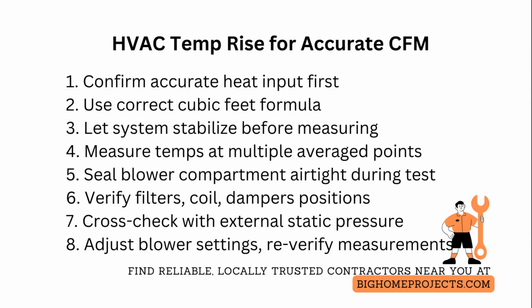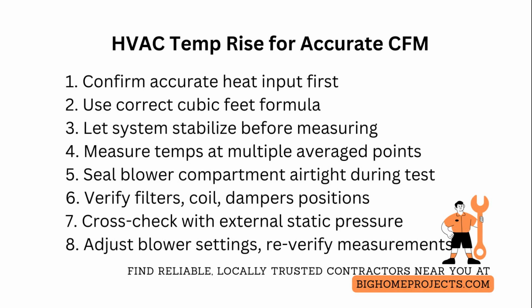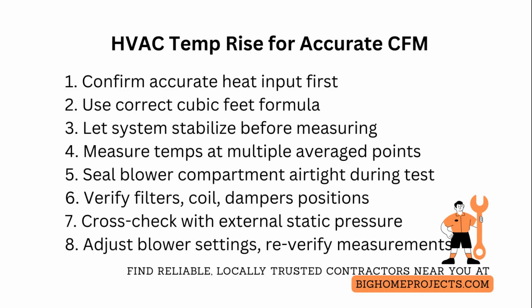Clock the gas meter for natural gas, or verify nameplate electrical heat kilowatts for electric heat, then adjust for elevation and gas heating value if needed. Without accurate heat input, your cubic feet per minute will be off.